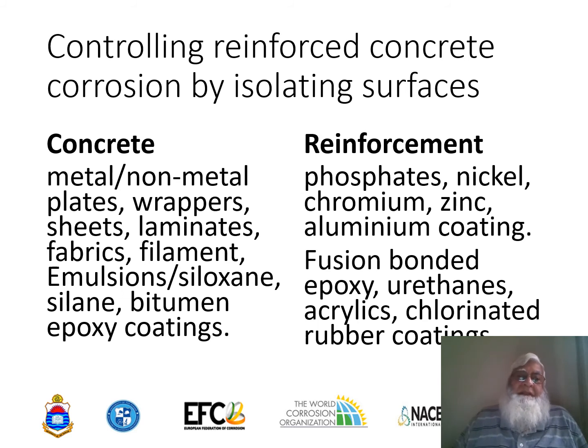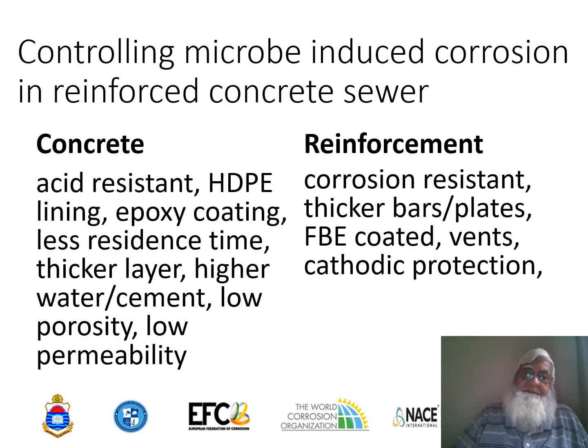Then there are the organic coatings which can be used in there, like fusion bonded epoxy coatings, urethanes, acrylics, and chlorinated rubber coatings. These are applied to the steel to prevent it from coming into contact with the moisture inside the concrete and to remain unattacked by the corrodants of the concrete.